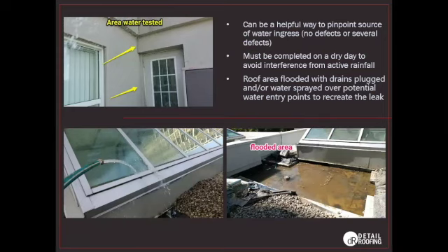So with the controlled water test, we would either flood the area or spray over different points that could be contributing to the leak to try and recreate it and determine which areas require repair.